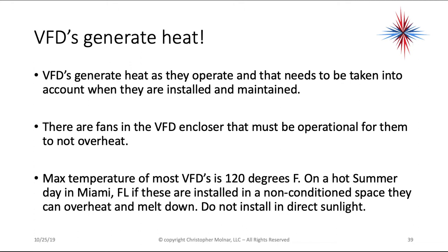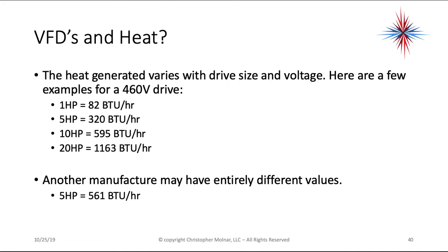On a hot summer day in Miami, Florida, if these are installed in a non-conditioned space, they can overheat and melt down. You do not want to install these in direct sunlight. The heat generated varies with the drive size and voltages. For example, one manufacturer specifies a 460 volt drive.